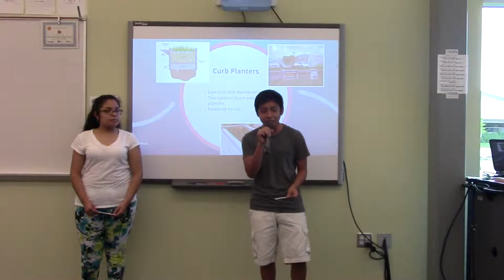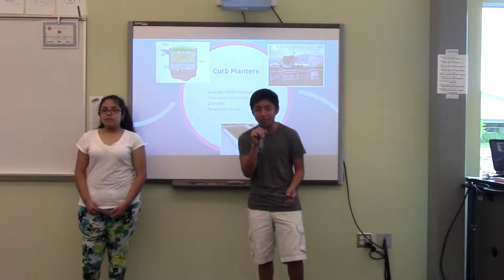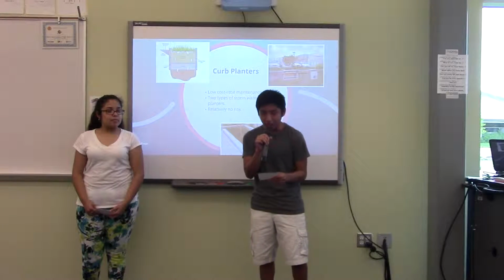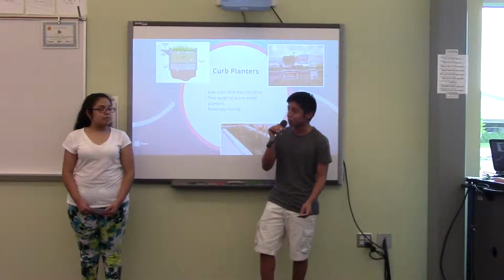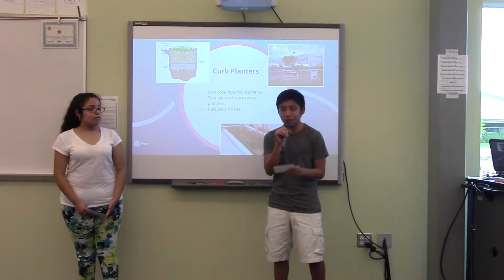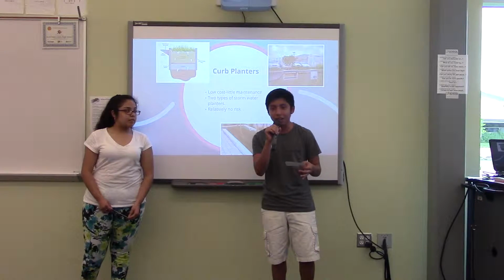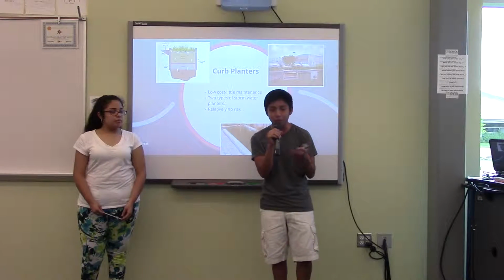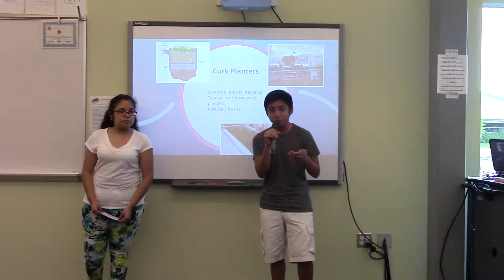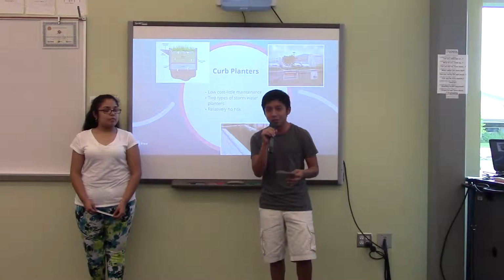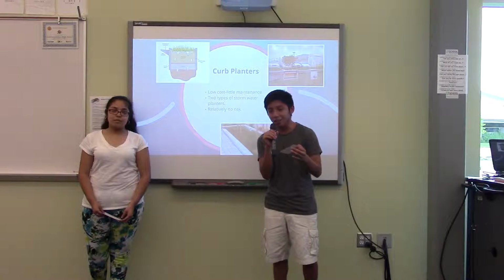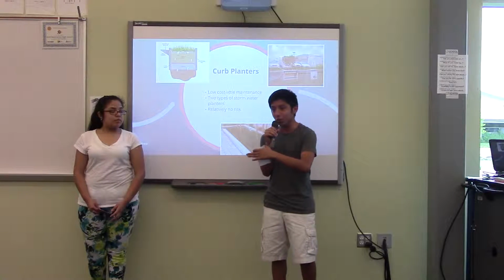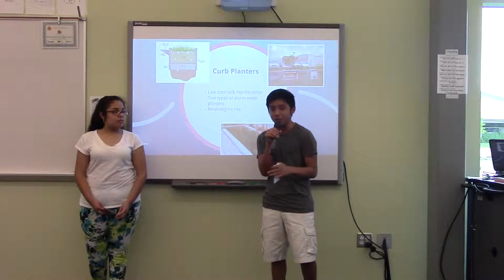And curb planters improve water quality, they provide shade, they prevent floods, and they are aesthetically appealing, and they also add property value. And there are basically two types of curb planters, infiltration planters and non-infiltration planters. Infiltration planters allow the water to soak into the ground, and it cleans the runoff from buildings and other things. And it also replenishes the source of groundwater. And non-infiltration planters allow the water to go through, and it'll eliminate some of the runoff, and then it'll just allow it to go through the drainage systems into rivers and other things.